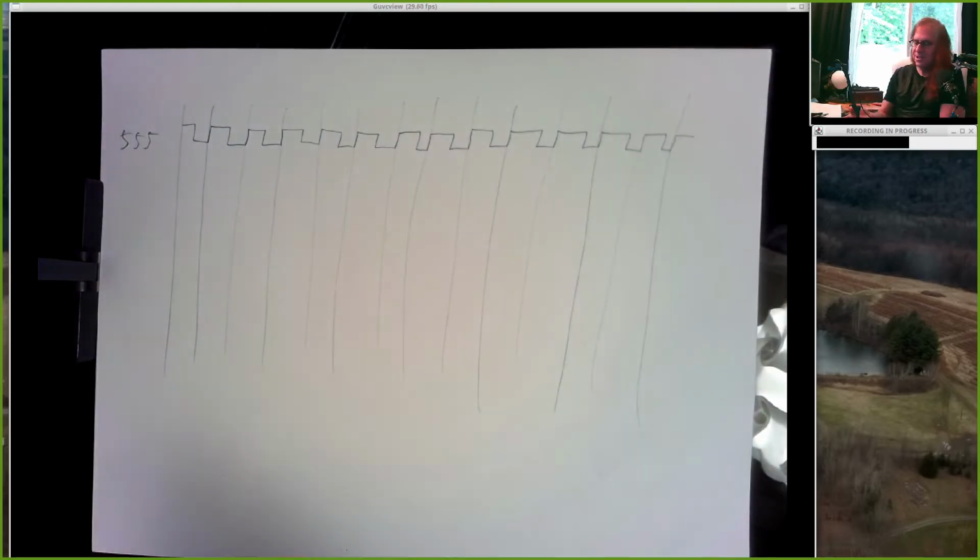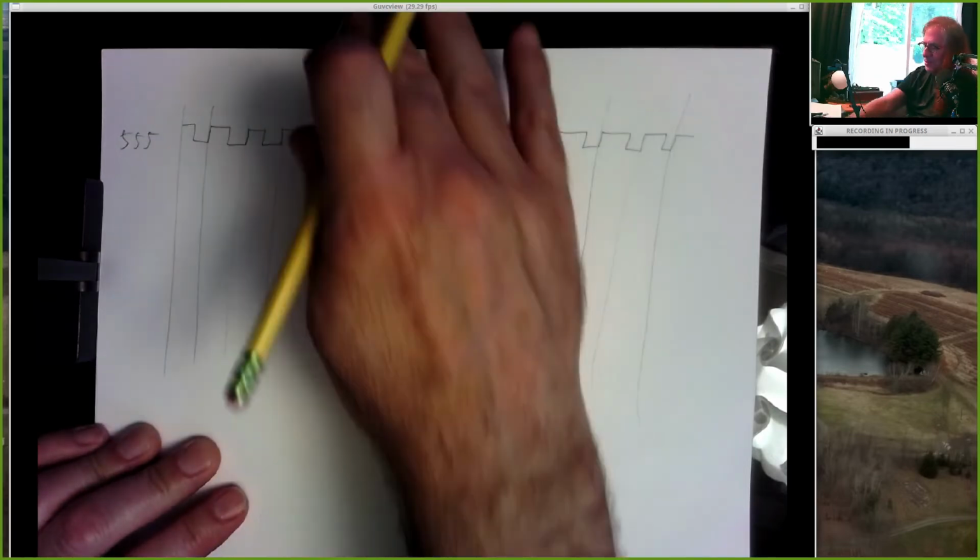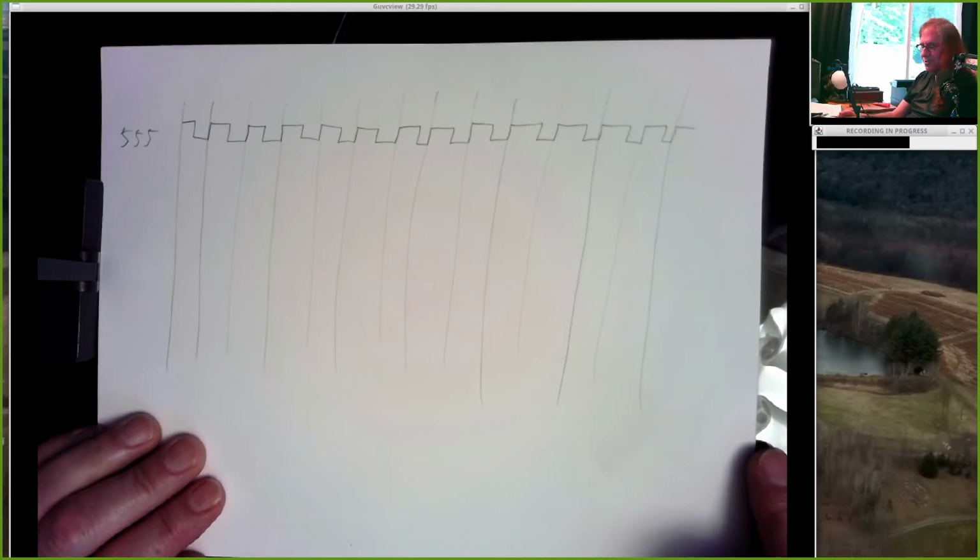So you want at least 10 cycles of your system clock to be able to show all of that behavior. And you probably want at least 11 because we always want to see something moving from low to high back to low, or vice versa, so we can see what's happening on either end. But show a bunch of cycles.